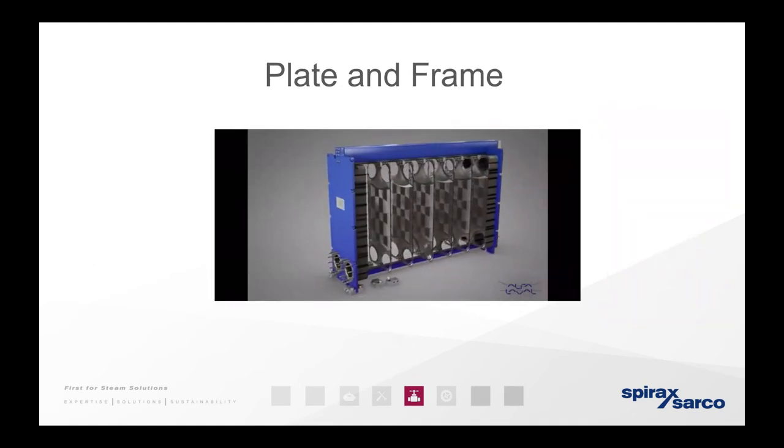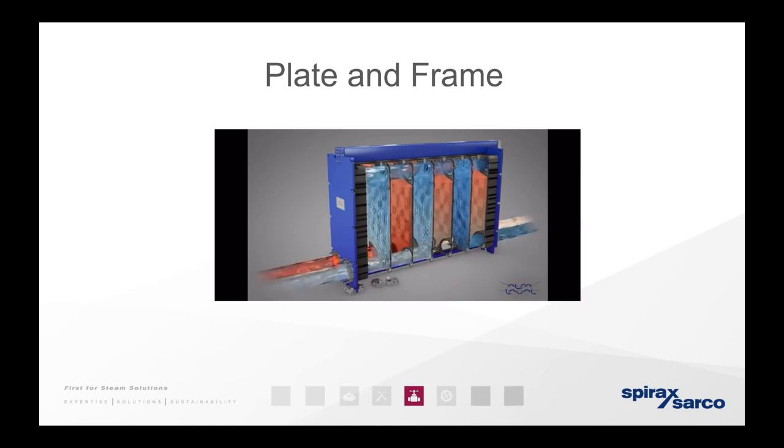So onto a plate and frame. As you can see on the video here, this is the design of a plate and frame. So you have the frame, which is the blue, the plates in between. Liquid comes through the plates, heats up, spreads through the plates, and then back out. You have your media, your secondary media, which you're trying to heat. The other side of the plate, you have the heat transfer coming through on the other half of the plate and through. So it's a very simple design, very easy to fix when they go wrong, if they go wrong.